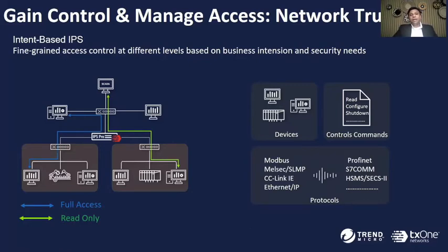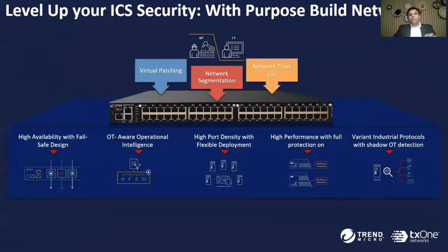I may have my maintenance people connecting through the VPN. So I want to enforce a control to say, whenever they connect to the VPN to access some of my devices, they can only have read access. They cannot change anything. To my devices, nobody will have reboot access, shutdown access, and so on. So you can actually monitor, manage and gain control of what protocols can be accessed, in terms of read-write or reboot access commands, with complete protocol visibility, inspection and control over OT protocols. And all three can be applied on a single device.